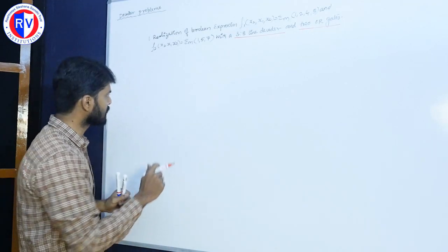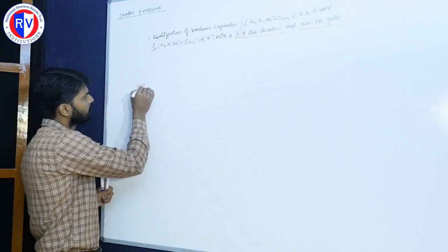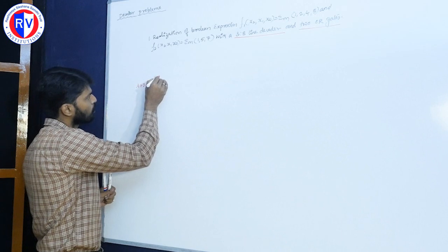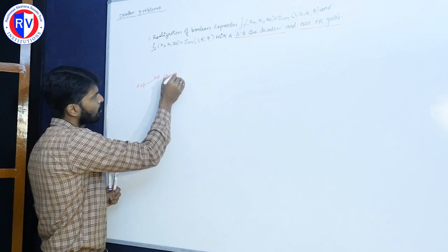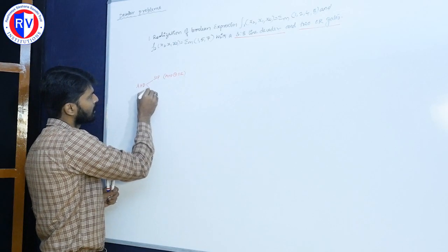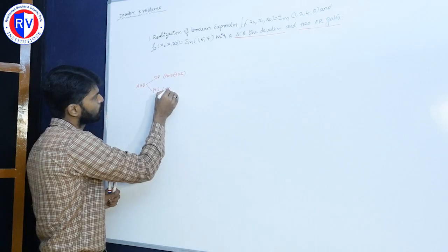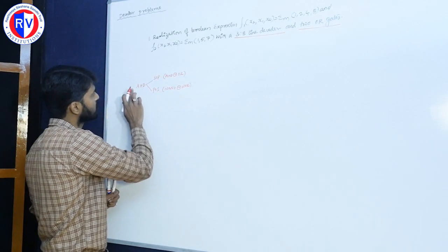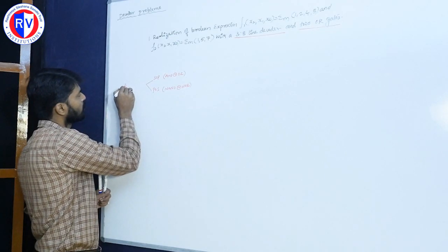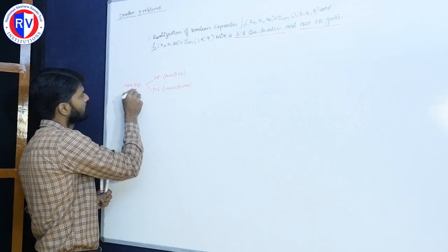From the basics we learned that if I take an active high decoder, in order to generate an SOP equation, I need to use either an AND gate or an OR gate. Similarly, using an active high decoder, if I want to generate a POS equation, I need to use a NAND gate or a NOR gate, isn't it? This is the active high decoder.